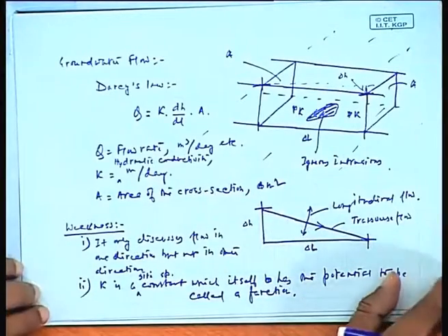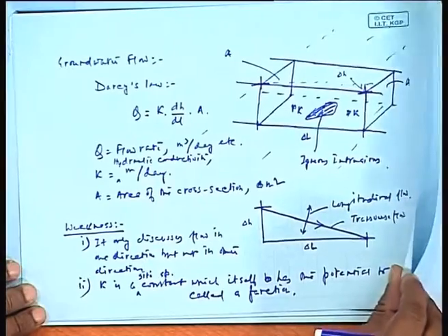To understand k as a constant over a length of aquifer, say about 2 kilometers, 3 kilometers, 4 kilometers, is too simplistic. K itself cannot be a constant. So k can be a function by itself. The nature of the functions can change depending on the construction of the materials in the aquifer, isn't it? But still, this is quite popularly used.